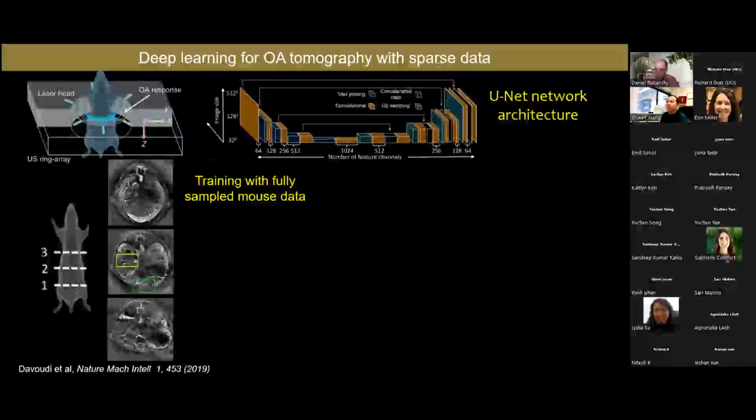So of course, it's clear that you better get a scanner with the best tomographic coverage for your application. But this could quickly become quite expensive as you need a transducer array with lots of elements, and then also all the multi-channel electronics to acquire all this crazy amount of real-time ultrasound data. So if you can't afford it, then a possible solution could be to acquire data with fewer channels, for example, if you do some sort of undersampling of the channels.